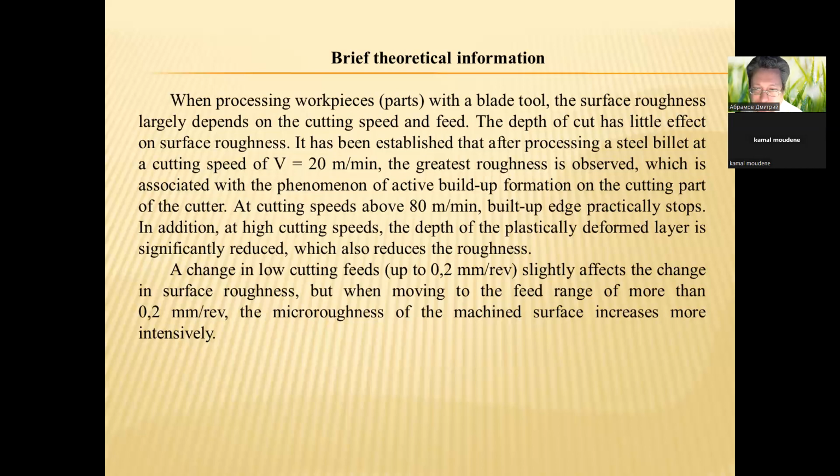But when moving to the feed range of more than 0.2 millimeters per revolution, the micro roughness of the machined surface increases more intensively.